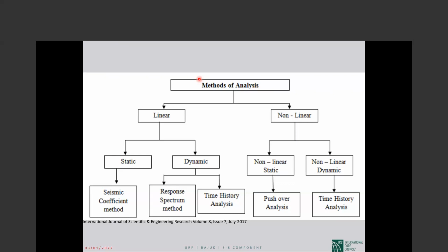The different chapters on different systems say that, for example, if your system is a moment resisting frame, in this beam, the bending moment is a deformation control, and all other actions are force control. So axial load is force control. This shear here in this beam is force control. This torsion is force control.